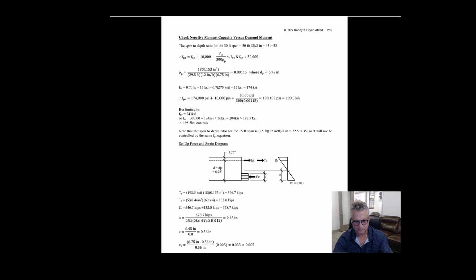So let's try. Okay, the last video, which seems like a long time ago, we came up with the minimum amount of bonded reinforcement, which is what we did to start with the beam design, and one-way slabs, same thing. In fact, you'll notice a trend here. A good post-tension design is governed typically by minimum bonded reinforcement. The flexural strength check is really just kind of a check. Sometimes we need to add a little bit more for strength, but that's more the exception rather than the rule.